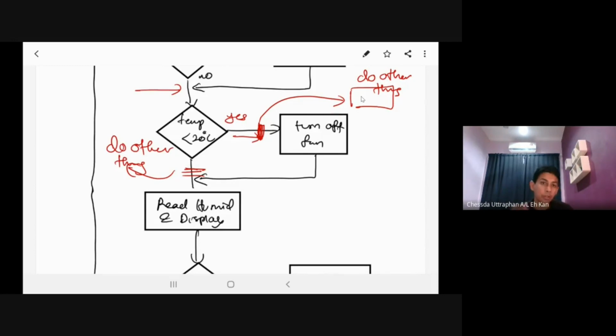The microcontroller runs based on the value inside the PC, which is increased in sequence. But if you change the value in the PC, it will force the microcontroller to jump to another location. That is the possible way to do that, by using interrupt.